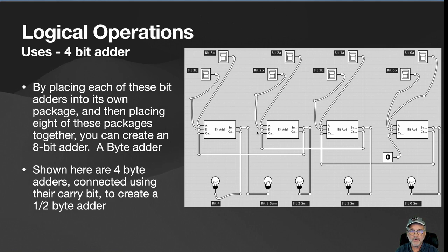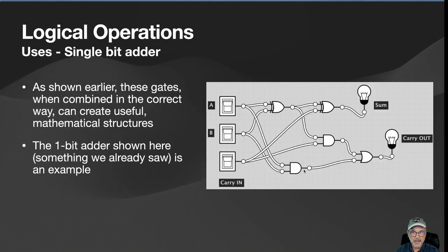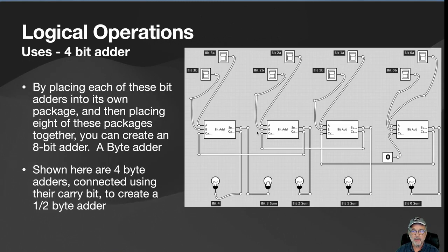So those are the bit inputs going to each one of these packages. Now that square box is the previous single bit adder. So we've packaged those into what we call a package, which takes 2 inputs, A and B. It also takes a carry from the previous bit.